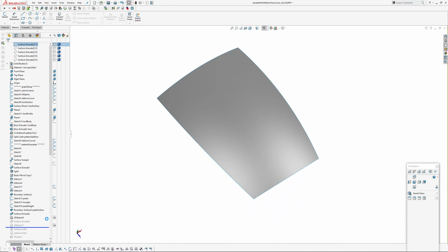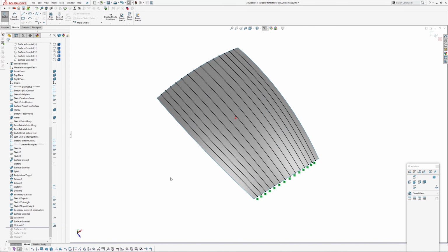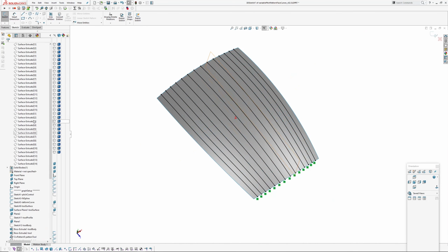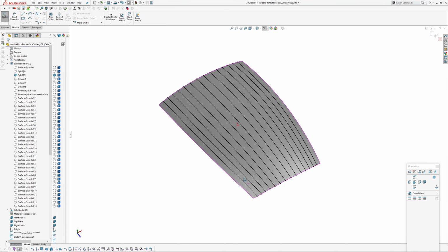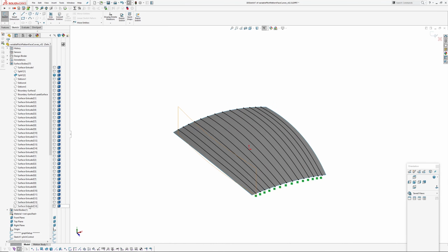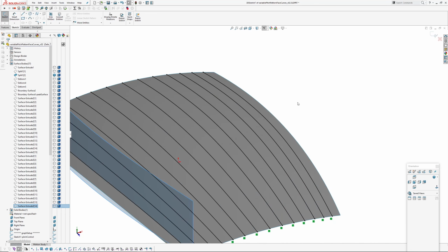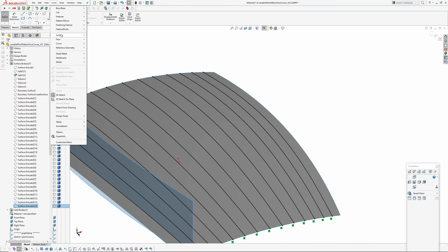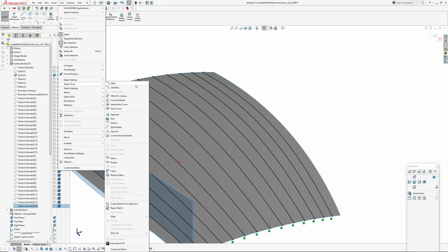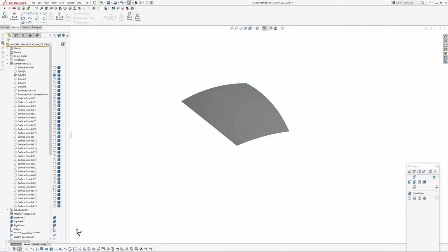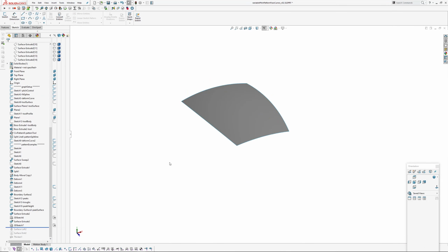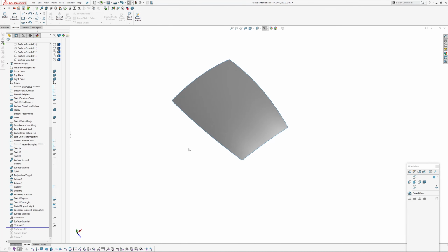And extrude 3D sketch. So these 3D sketches just extrude those lines up, and then you go up here into your surface bodies and you pick all the extrudes and the other surface you want to intersect, and insert, tools, sketch tools, intersection curve, and it does it in one go, because you can't project those curves on because it wants them to be one continuous entity.